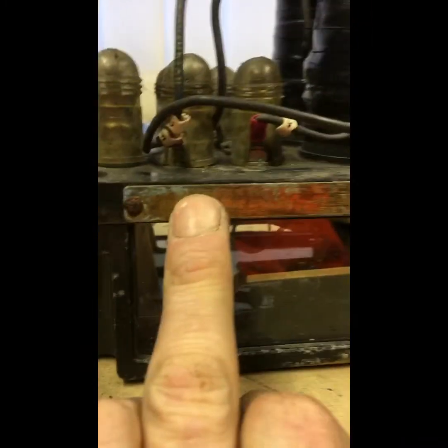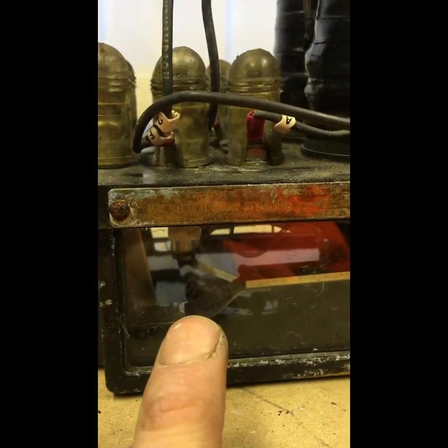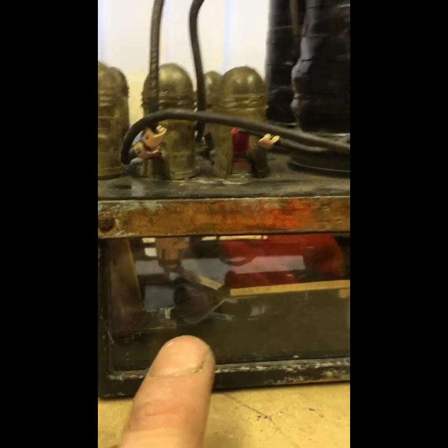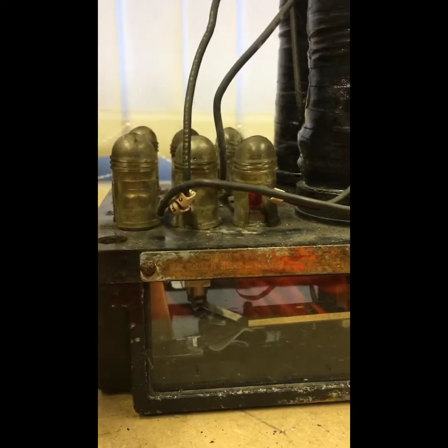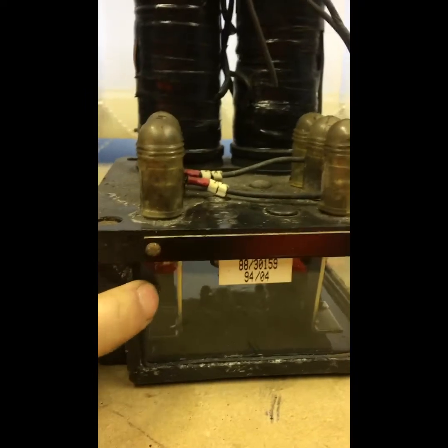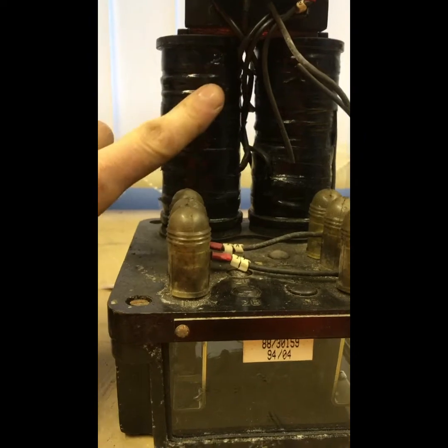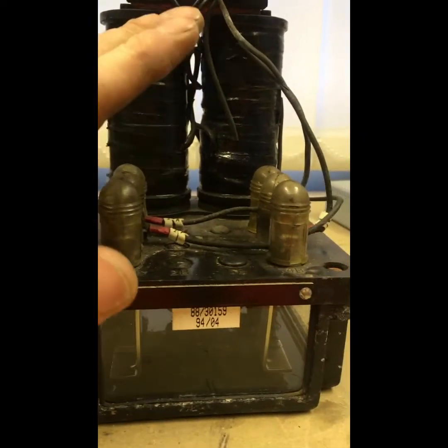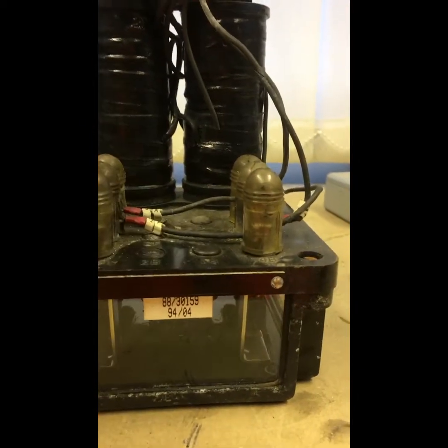D3s and D6 types. So the way I remember this is a D3 has a pick of roughly 0.3 of a volt, and a D6 has a pick of roughly 0.66 of a volt. So you can kind of work them together. D3, 0.3, D6, 0.66. And one of the unwritten rules of thumb is you never put the track voltage over 1.5 times the pickup voltage, otherwise you will saturate these coils and magnetise them up permanently. And then what will happen is, as you try and take the voltage off the relay with the train, it takes its time to drop, and you don't want that. You want a clean, quick drop.